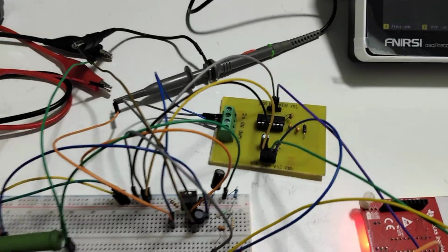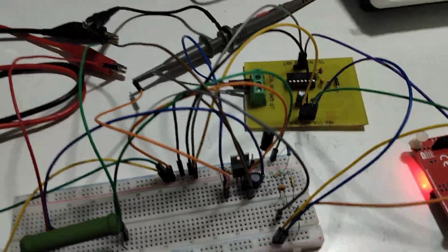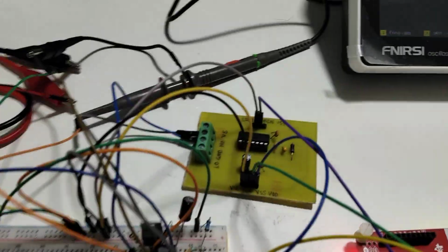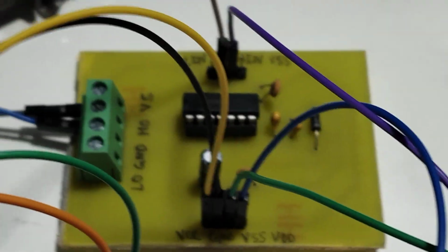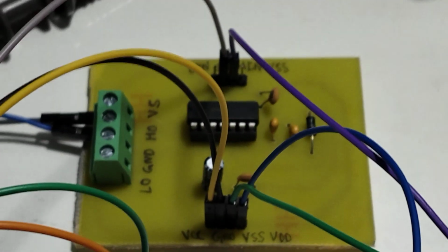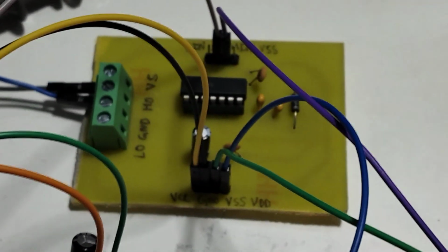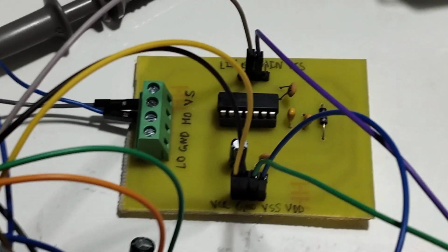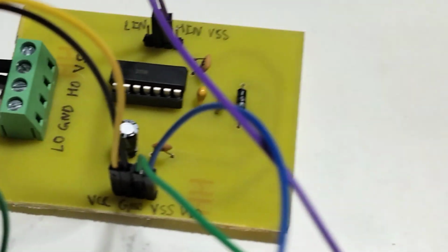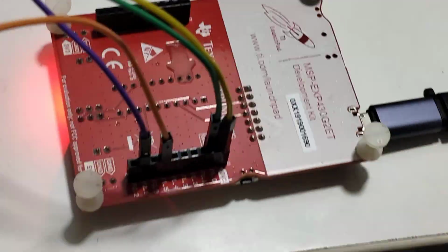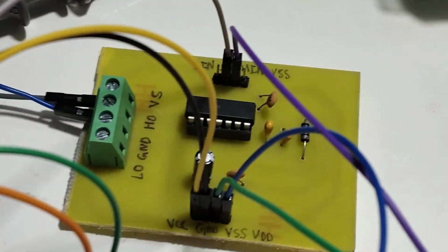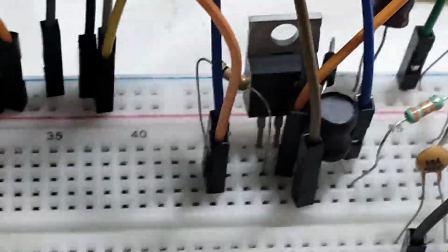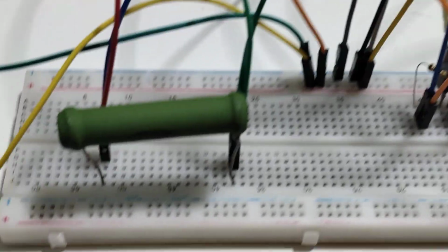Okay guys, this is the hardware, and yeah, a little bit messy, but not too many components this time. The big part is, since I made the small PCB for the driver board, it's simplified a lot of the problems which I was facing before, so this is good. It has the screw terminals and all, and this is the IR2110. So yeah, this is the MSP430 board, and we're sending the PWM over here, and this is the actual power converter. There's our MOSFET, our inductor, capacitor, and the 10 ohm resistor, and the load is here.